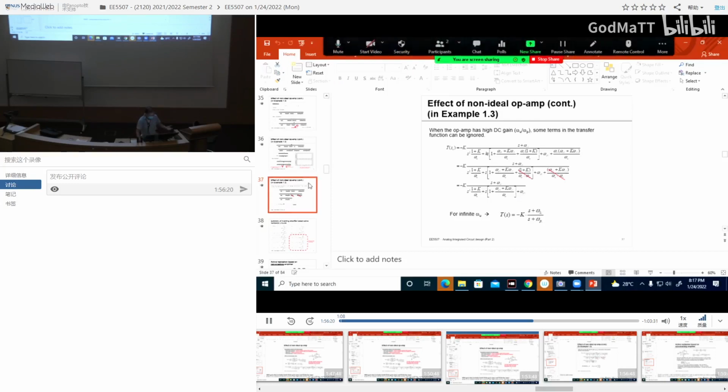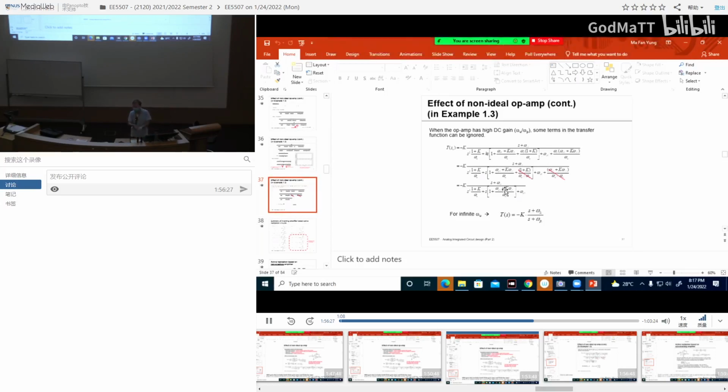So now in our real op-amp, we got a complicated equation. If we apply back the simplifying assumption, what happens if the gain is very high? What happens if the bandwidth of the op-amp is very high? We should get back to the first one. So you ask, what is this thing useful for? Yes, it's useful. Because when you analyze something with a real op-amp and you get a very complicated equation, how do you know whether it's correct? How do you know whether you made a mistake somewhere? You apply this test.